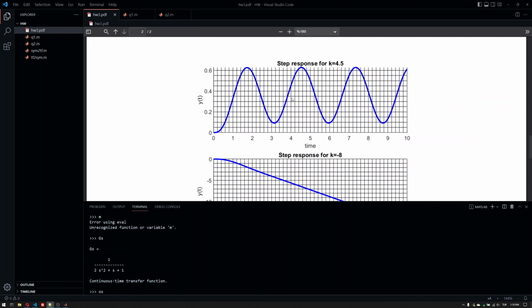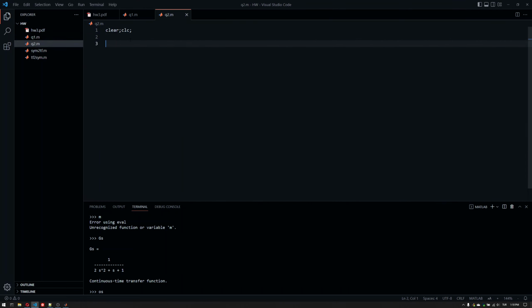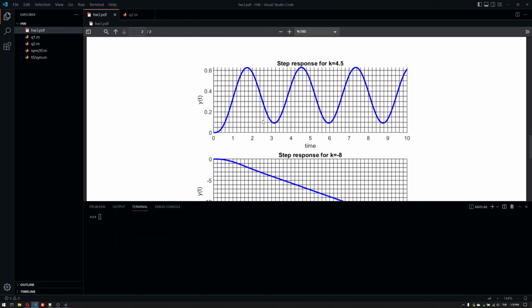So again, for the first step, we need some measurements. And this time around, what we are going to measure is, so let me clear the console. This time we have a sinusoidal wave. And what we need to measure at this point is basically the period or the frequency of this, because sinusoidal waves make sense if we have a period here. So I'm going to take this lower part and this lower part, and measure the difference so that I get just the period.